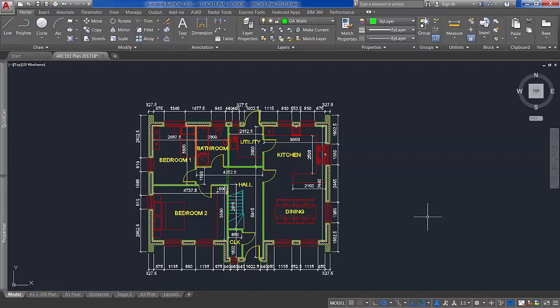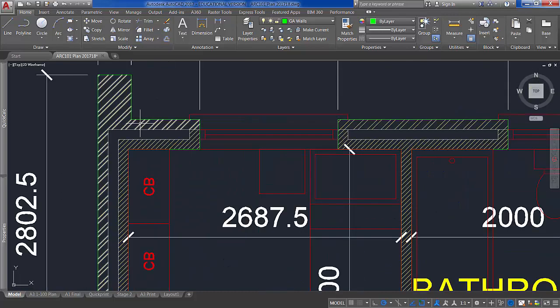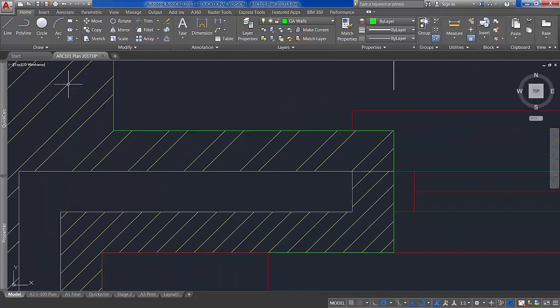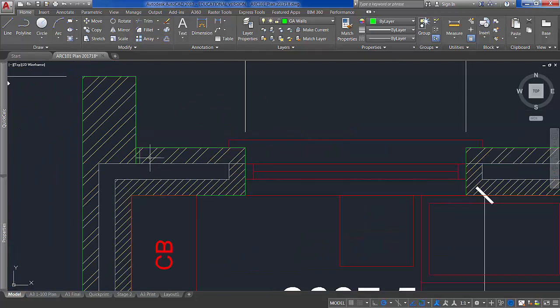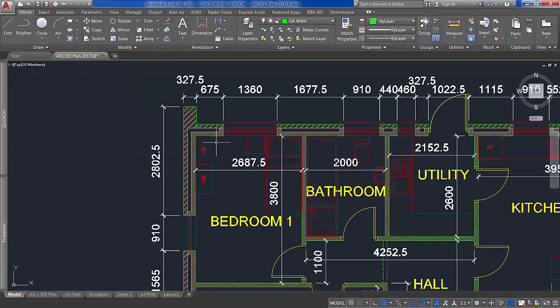Also, you should be adding in things like smoke detector, heat detector, carbon monoxide detector, and things like movement joints. So for example, with a movement joint, you might want to put a movement joint in here somewhere. There are different ways of showing this type of thing, but you can show double set of lines and then just maybe add in a little text annotation.